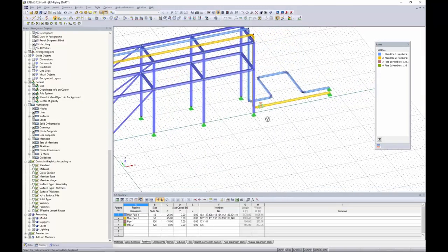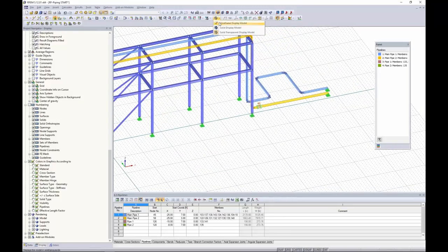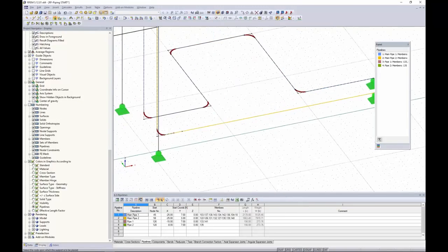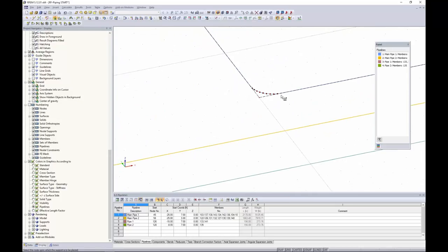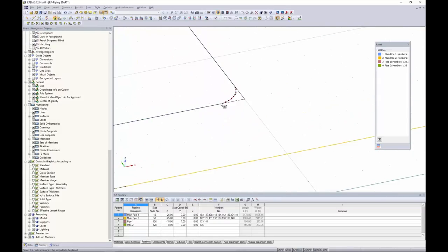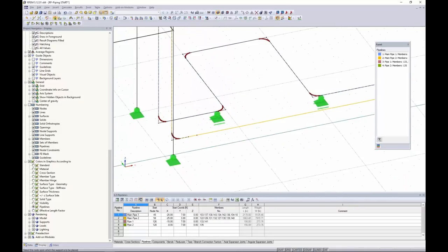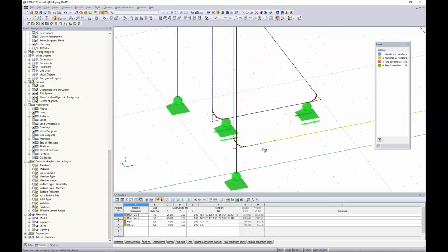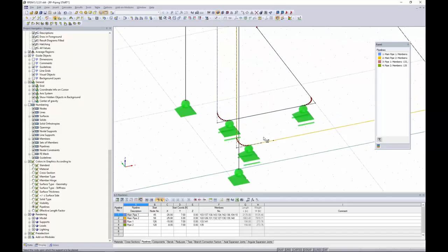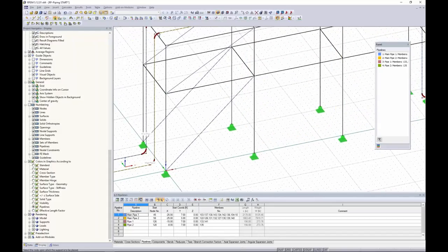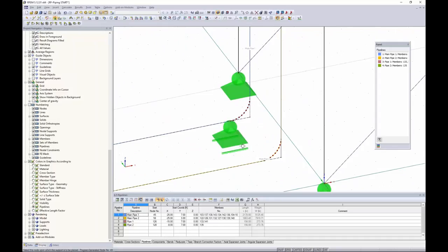So now for this type of support, I'm going to turn this into wireframe view, and I'm going to zoom in here. And these will want to be applied right at the bends of the pipes. Now I'm not applying it at this node, which kind of indicates where our bend occurs, because this node doesn't technically lie on the piping member. We need to apply it directly on the pipe. So for this, I'm just going to highlight these nodes right at the bends on both sides. And once we've completed the right side of the structure, we'll zoom in to do this on the left side.